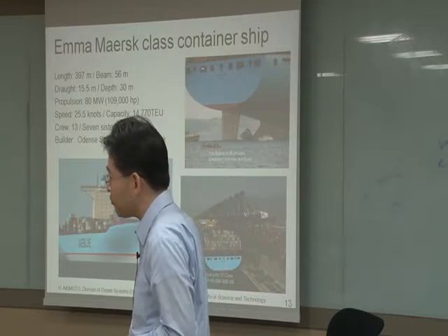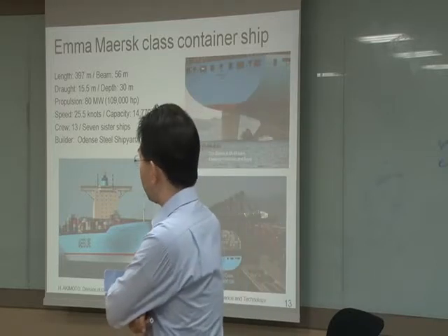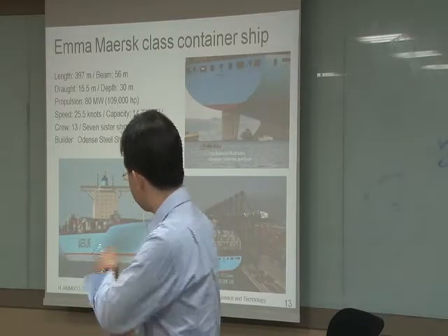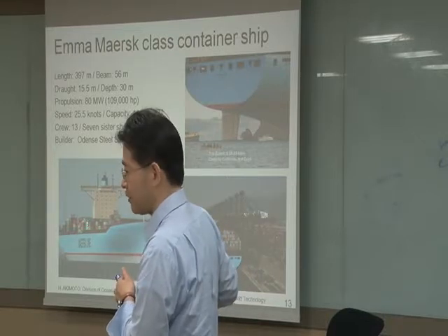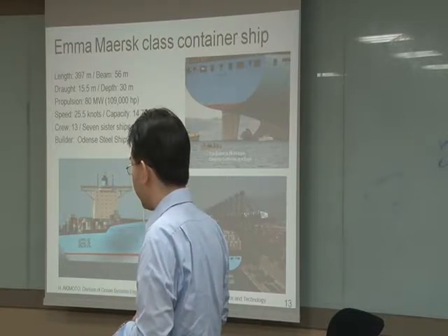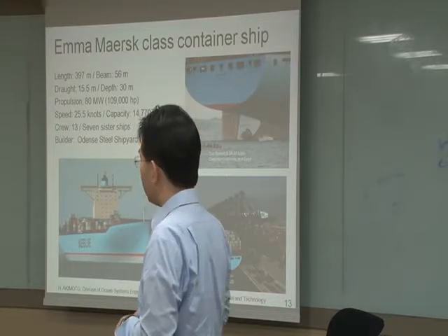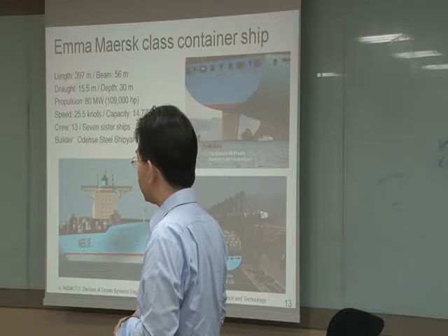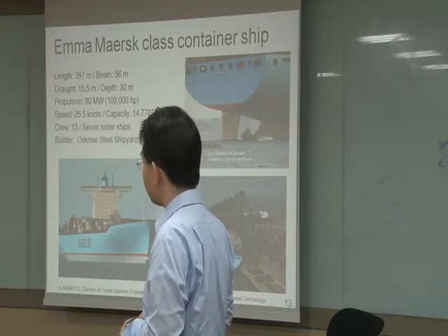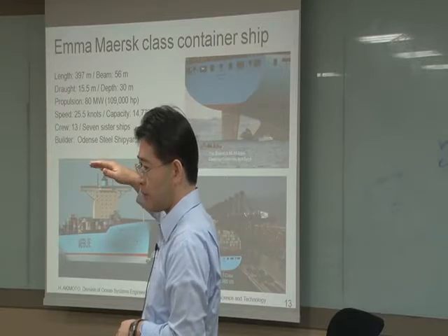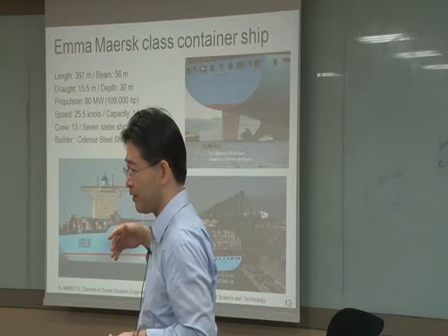In container yard, you mean in container yard? It depends on container yard. It has regulation. On the ship they have girders, but usually we don't have girders in container yard. So in my experience, in China they are stacking 5 containers, but it is 3 in Japan because we have earthquake.